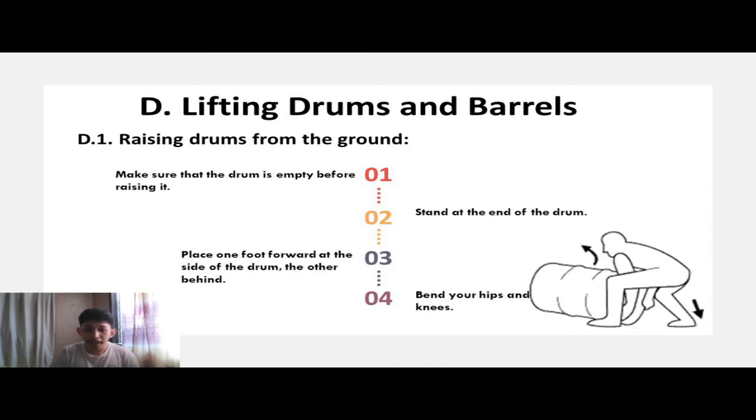So we need to first inspect the material or the drum before we do the other steps in lifting it. The second thing to remember is to stand at the end of the drum. You need to stand on the other end of the drum, so you will be preparing yourself in raising it.